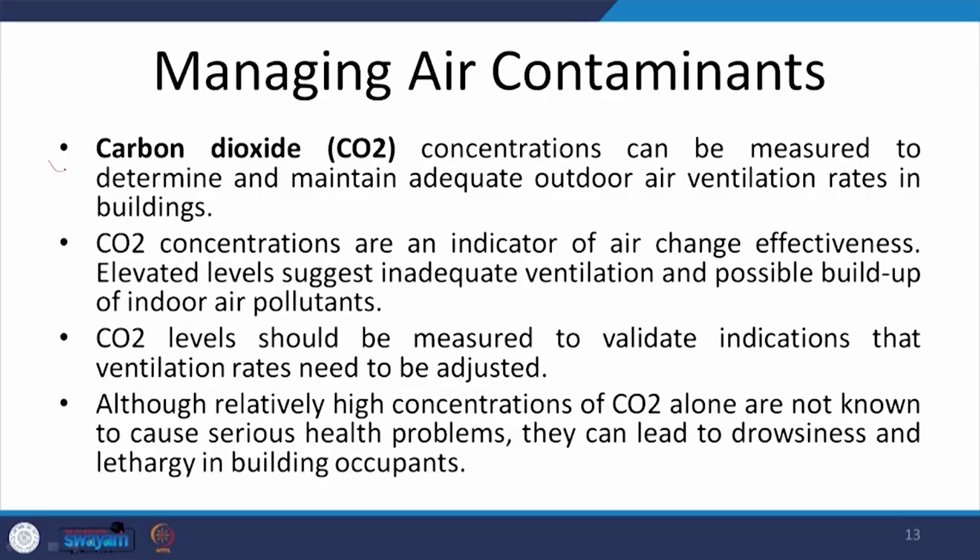The next important parameter is carbon dioxide, and managing its level. We have also already seen that there is a threshold limit of 1000 parts per million of CO2 in the indoor environment.